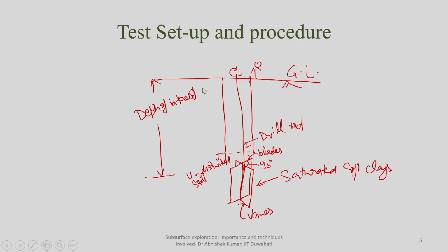You went to this depth, just like any SPT test or rock sampling, you are interested to find out the strength properties of the soil here. You start rotating it, depending upon how much is the torque. So, you are having some way to measure how much is the amount of torque you are applying here. As a result of this torque, what will happen? This will also start rotating.